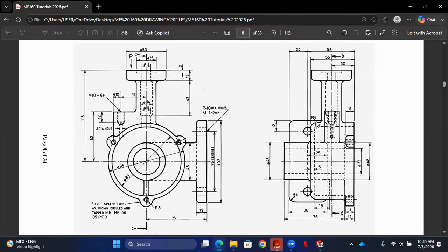Now this line over here is in line with this, and this line is the tip of this circle. So I can extend to the tip of this circle, the diameter for this circle is 95. Because I've cleaned this side already in my side view, I'm just going to extend this horizontal line over this center line, measure 47.5 to the top, and then draw my vertical line to meet. And then I'll measure 29 and then draw this line over here. That's what I'm going to do.